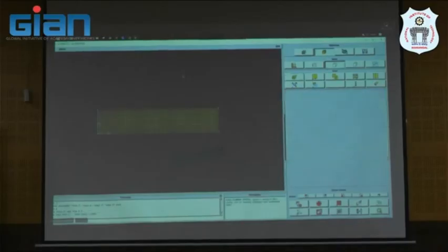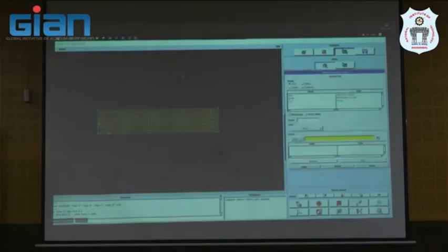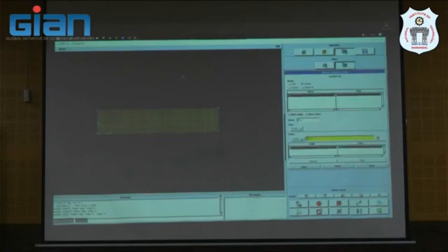and after that we should define the boundary names of this geometry: the inlet is one, the outlet is one, and the wall, top and the bottom. And after that, we should define the simulation domain. We can choose if this simulation domain is fluid or solid. In our case, it is fluid.